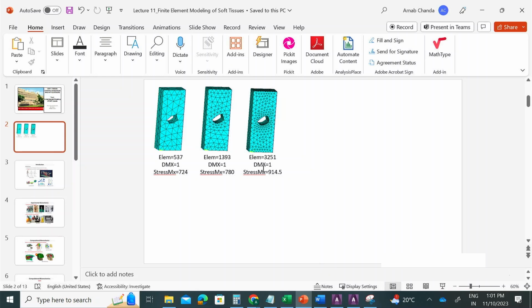We want the mesh to be accurate. The results should not be changing due to the mesh. It is a little bit of a hit and trial technique, so there is no clear path on whether you should take 5 meshes or just increase the elements by this time. There are some rules of thumb, like you want to increase them by certain intervals, and usually beyond 10,000 is when the results tend to converge in most simulations, right? So we'll do that.